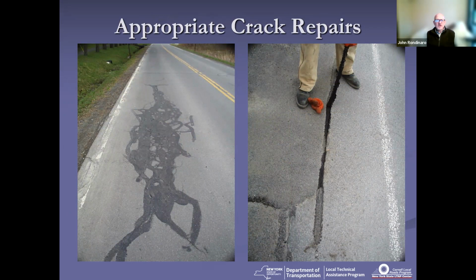You're also going to look specifically at your cracks, and in terms of the left-hand slide, when you see a pond of asphalt like that, even not thinking about your overlay, that's a nightmare. That's an accident waiting to happen. And anybody on two wheels, anybody that rides a motorcycle hates to see that. You hit that with a drop of moisture and that turns into a skating rink. And then taking accidents off the table, you hit that with your overlay material, and that's going to make a big gooey mess, and it's going to raise hell with your overlay.